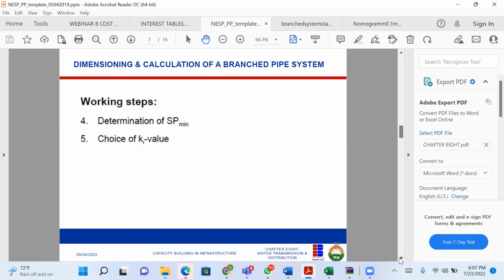Once you are able to satisfy the person living at the 4th floor, the person living at the 1st floor will never have a problem, because once water is coming, the pressure will reduce as it goes up, right? And you don't want that pressure to reduce. So you need to use the person at the 4th floor to do the design.